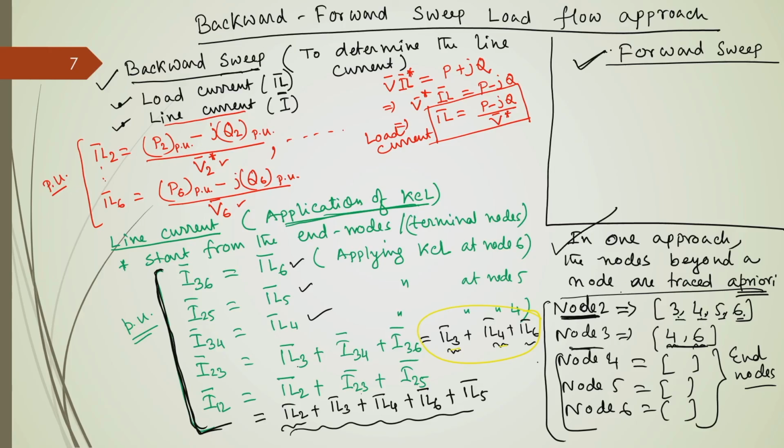Then you come to this forward sweep. Forward sweep is to compute or to determine bus voltage, okay. And this is by application of KVL, and that will flow through the forward direction.